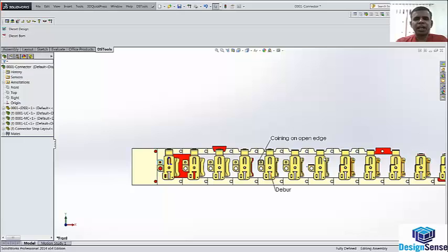This is a laid out strip that is generated from 3D Quick Press. Now, to manufacture this strip, the tool designer has to decide what kind of die set to be used, as well as the materials and other paraphernalia. Now, inside this, you see this pull down menu, which is the plugin developed by Design Science. It has a die set design as well as a die set BOM. Now, to manufacture this, let me start by initiating die set design.